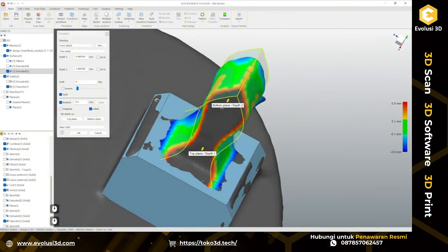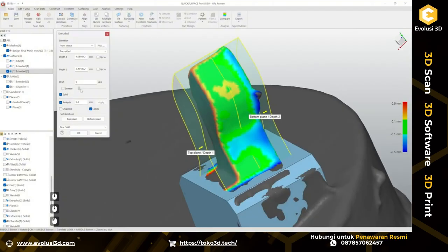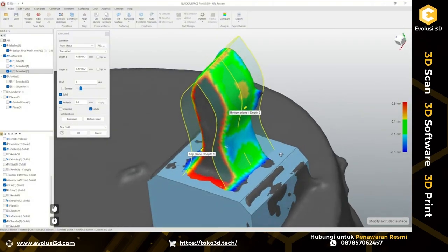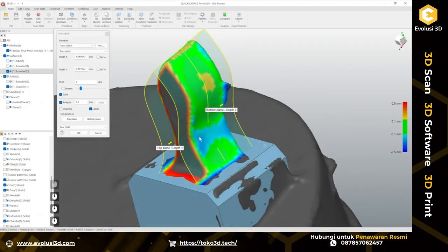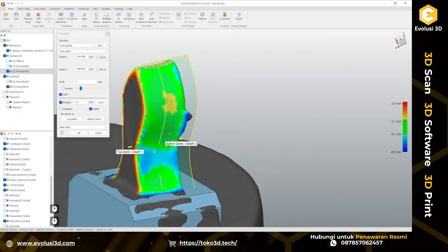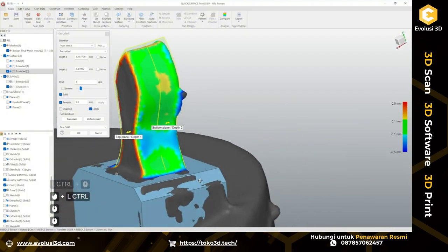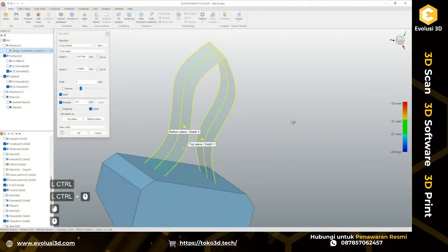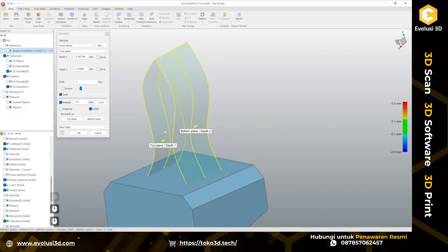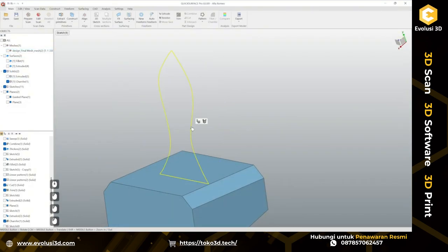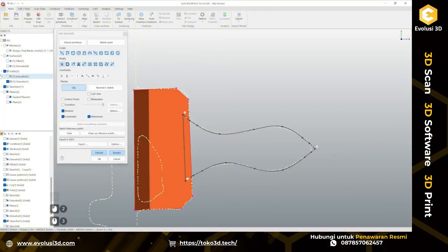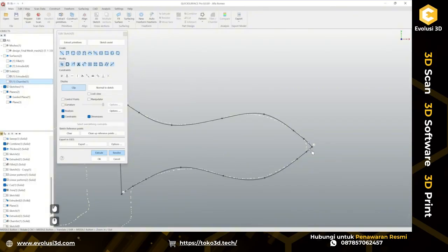Not that bad, we have some slight deviation. Probably we can try to play around with draft angle to get it slightly closer. So let's snap this side here. Okay, so we don't see actual deviation right now on the top and bottom surface, and most likely that indicates we're extruding a surface right now, and probably there is some reason for that. So most likely we don't have closed profile somewhere.